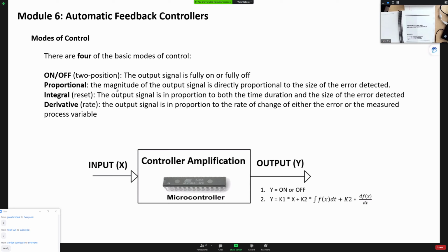The on-off control is not considered continuous control. It just turns on, reaches the temperature, turns off. Below the setting point, they usually have a dead band or limit in there. I think in motor control, we call that a cut-in and a cut-out. So if you reach the cut-in, it will turn on. If you reach the cut-out, it will turn off, those type of things.